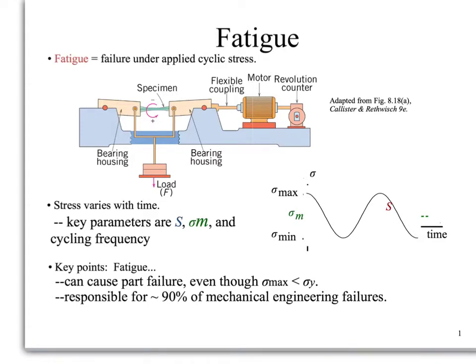To start off, we'll give a definition of fatigue. Fatigue is a form of failure that occurs in structures subjected to dynamic and fluctuating stresses. This fatigue is the largest cause of failure in metals, surprisingly. Also, fatigue is brittle-like in nature, even though it applies to normally ductile materials.